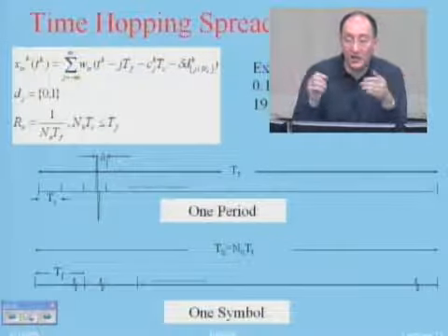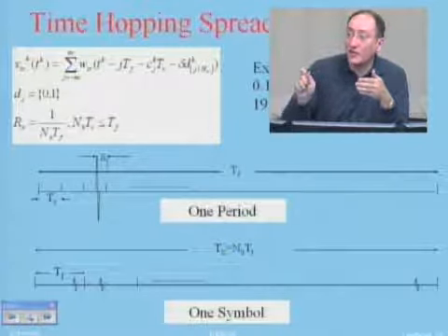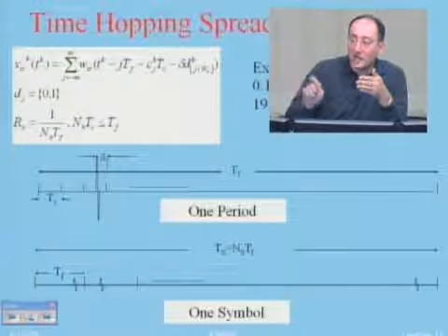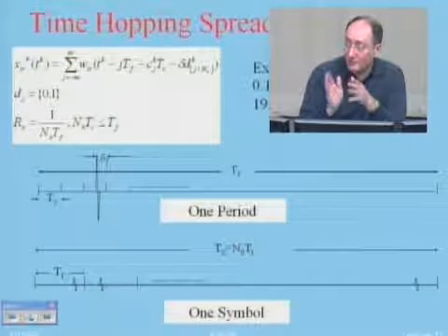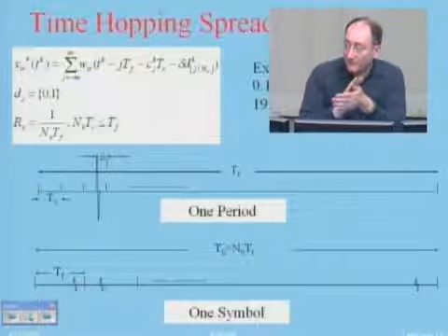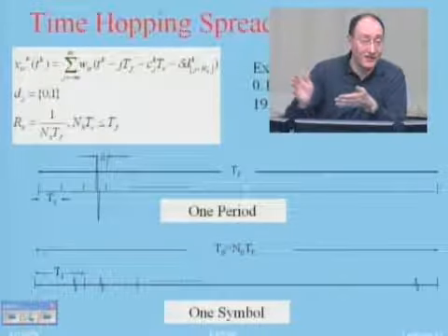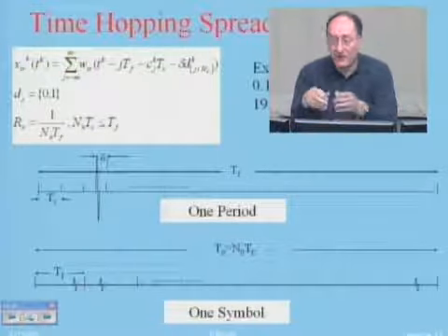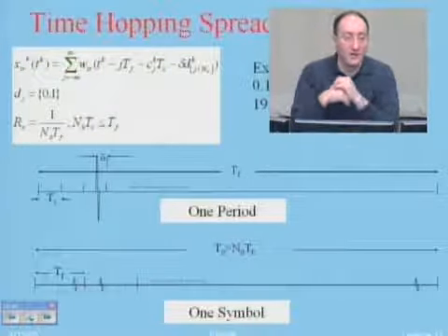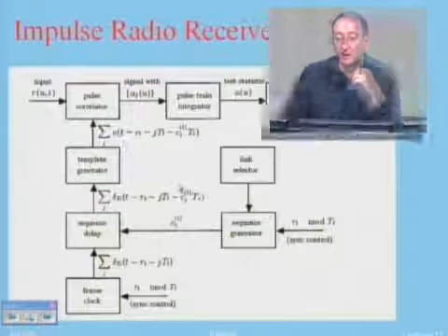So at the receiver, then I create two sets of pulses. One, the ones with delay, and one with no delay. And I multiply the received signal with these two replicas. Whenever they are on the same thing, they add. So I compare them to one another, and I say whether it was 0 or it was 1. And this is basically the same receiver.